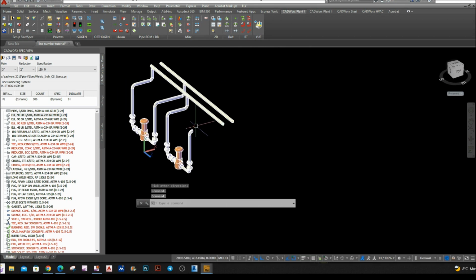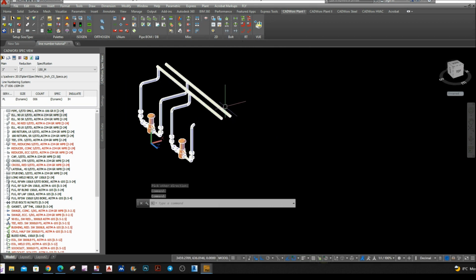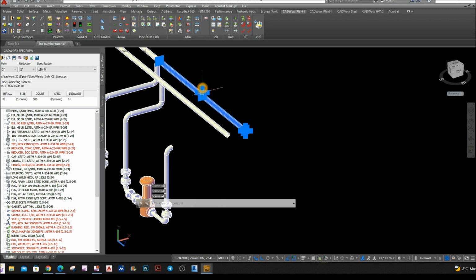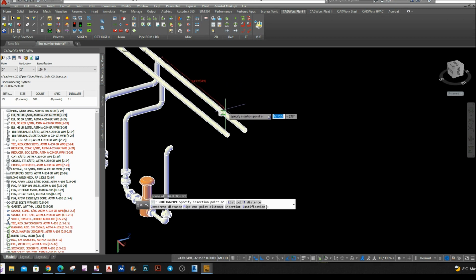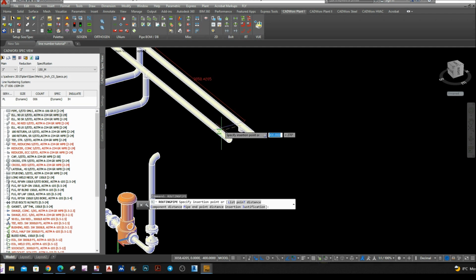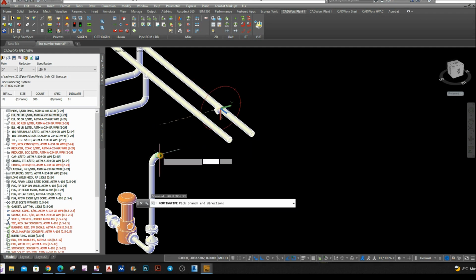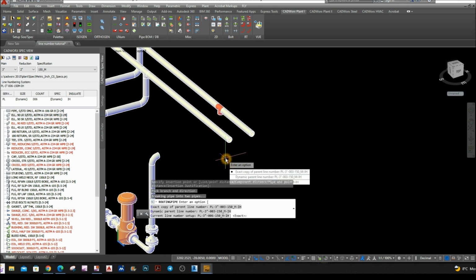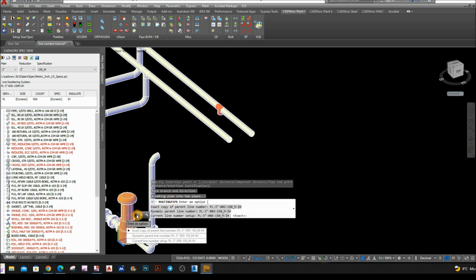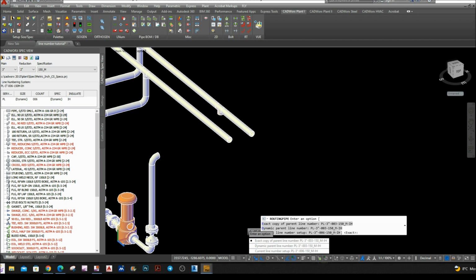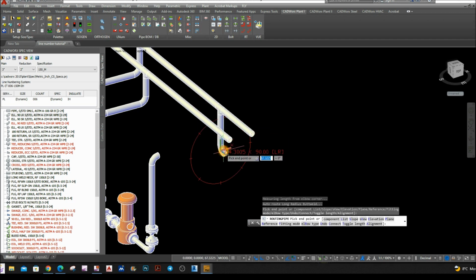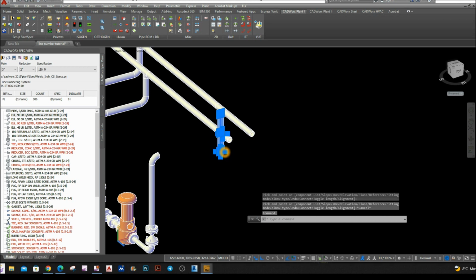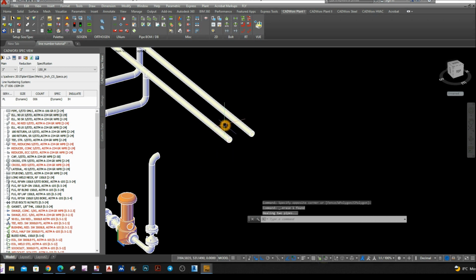Now I'm going to attach this end to this pipe. So I'm going to click this pipe here and click that plus sign, and it's providing a T. I'm going to align the T to this endpoint. So just snap that and bring it downward. And AutoCAD is asking you for, I couldn't see it. I'm going to bring this down here somewhere. Okay, again. I'm going to bring it downward. Okay, again. All right, click that plus sign.